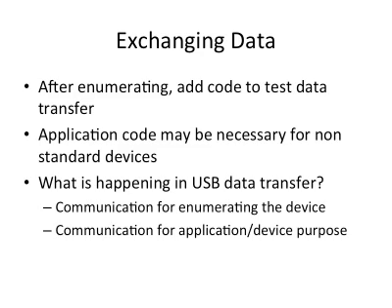Exchanging data. After enumerating, the code to test data transfer has to be designed. You probably will need to write application code for non-standard devices. What's happening during the data transfer is in fact the exchange of USB messages. These include communication for enumerating the device, and also communication for application and device purposes.